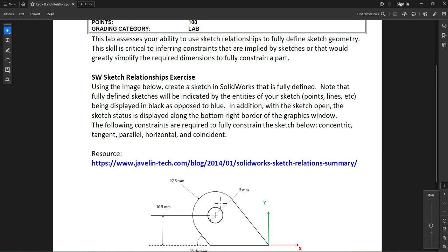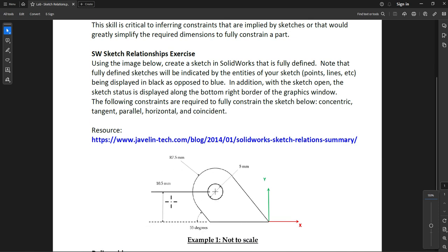There's two ways we can use the dimensioning, which you can see in this picture below here. They have the various dimensions set for the arc, for the diameter of this little circle, and the height of this figure itself, as well as this angle here. But there's also something that you can't see going on in this picture, but there are sketch relations happening. And when you make sketch relations, if you were to ever change any of the dimensions on this figure, certain things would not change. They would stay in the particular relation that you assign to it in SolidWorks, which could be really helpful.